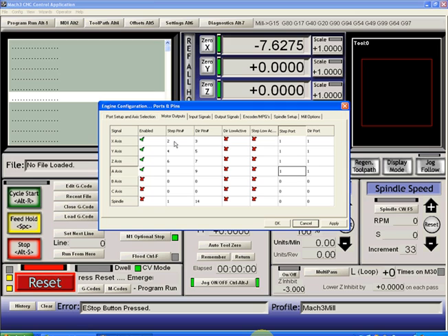When it comes to the settings for low active or not low active for a particular axis, you're better off leaving them unchecked until such time as you determine you have a problem. Many systems will run irrespective of these checkboxes. These are only necessary for some systems which are a little pickier as to whether the voltage is going high or going low at a time when the commands are being sent out.